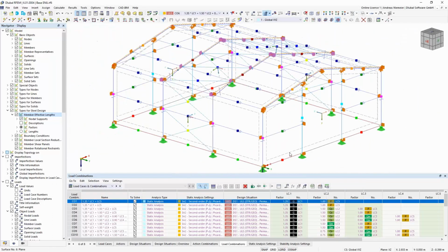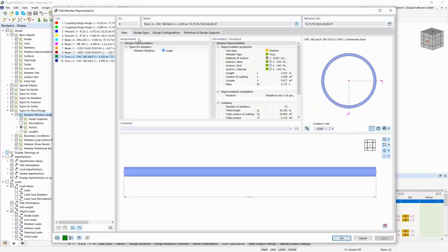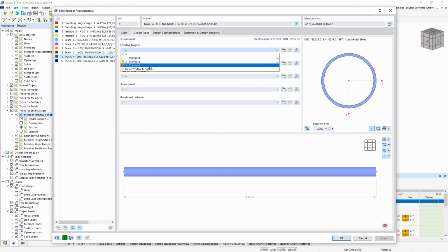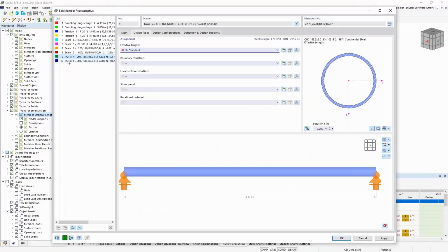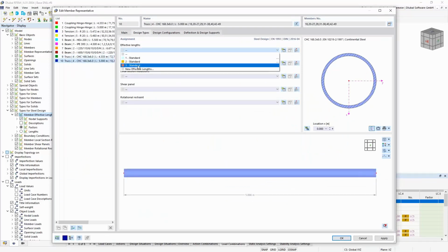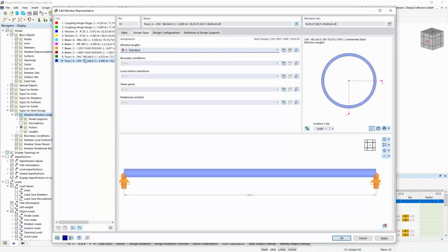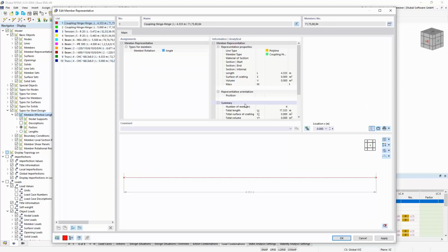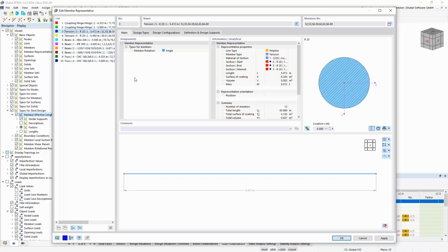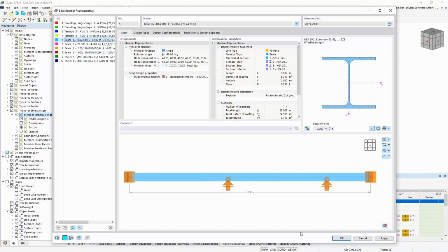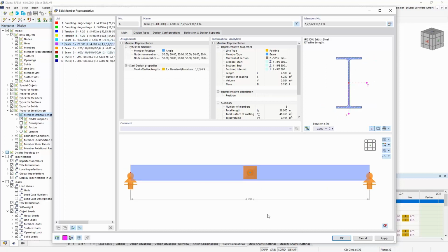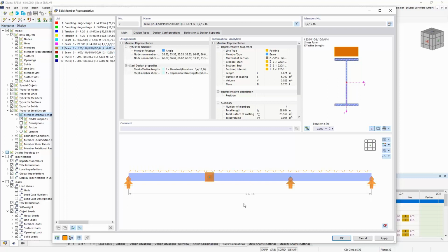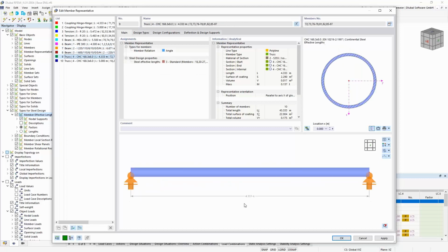Now the only thing that is missing is maybe these bracing members, and here we can take the same setting like for the last one, and even for the last representative we can also take this setting. And if we check now all positions, you see coupling members we don't have to check, tension members also not interesting for bracing. Here this member is braced in this direction, this member here, here we have also this shear panel.